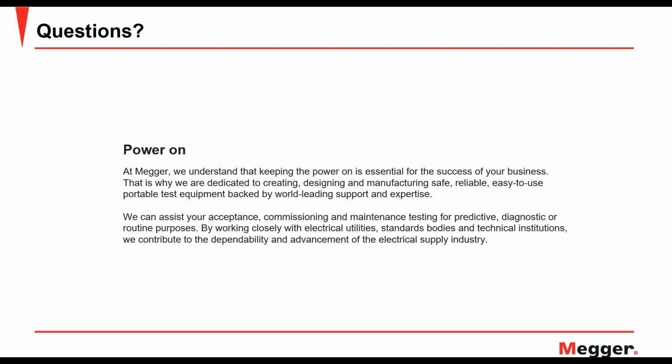I would mention, however, with regard to winding voltage, when you get to the lower voltage windings, and you saw this in Sanket's presentation, the transfer function, the dB plot of the magnitude of that transfer function for a low voltage open circuit test is generally scrunched. Sorry for the non-technical word. It's really pushed to near 0 dB. It doesn't have anywhere near the impedance of a higher voltage trace.